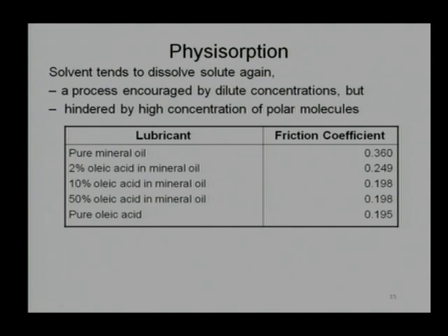So, what we are trying to convey is that an effective percentage should be utilized, we should not keep on increasing the percentage. I talked earlier about chemical absorption being harmful, and even for physical absorption, because oleic acid is costlier compared to mineral oil. If I keep on adding this kind of additive, the overall cost of the lubricant will increase, which is not desired by a number of customers.